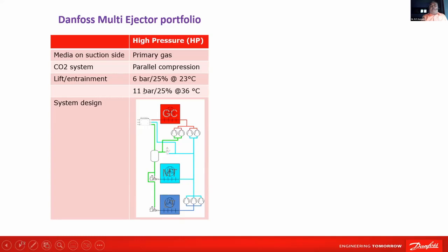Now, if the pressure difference is 11 bar, just putting some dummy numbers, if we were running this compressor at 10 bar suction, this one is working at 21 bar suction. So this compressor is going to give us much more capacity, much more energy saving as compared to if we did not have this. And that is coming because of the added ejector. Even you can do this without ejector, but because of ejector, it is further enhanced. Max available is 11 bar.